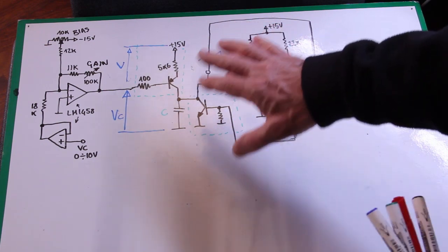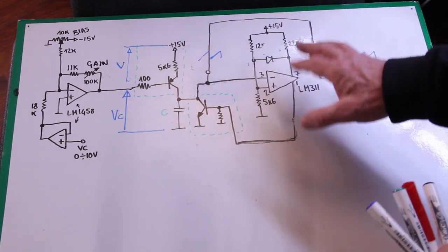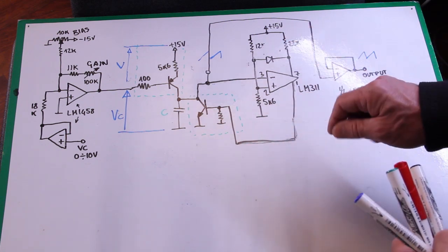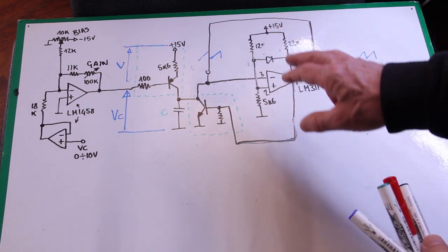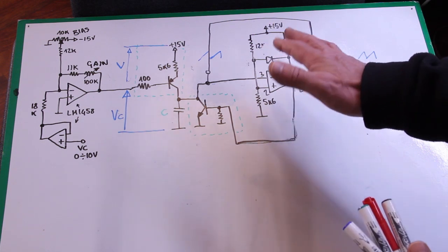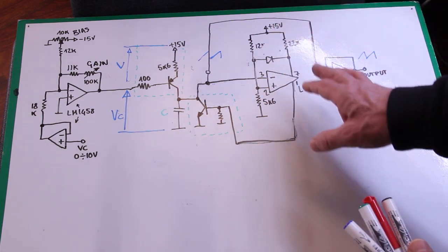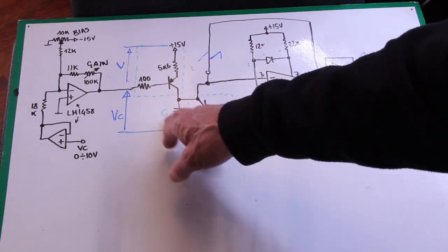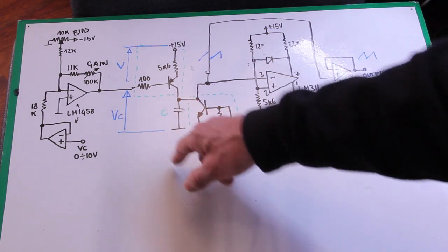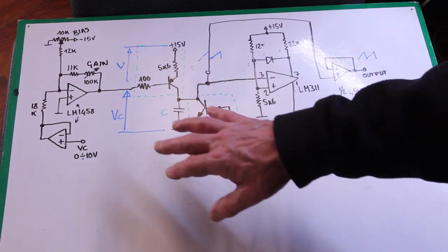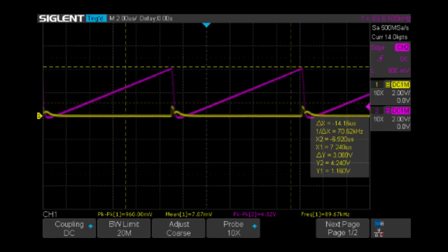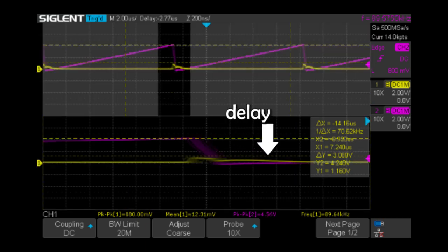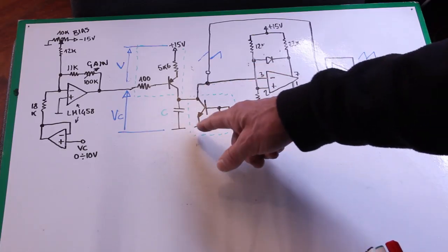First off, our circuit as it is now, while it is able to generate a nice sawtooth waveform, doesn't have a wide range of frequencies, as it starts from 50 kHz and reaches 200 kHz with a capacitor of 1 nanofarad, a frequency ratio of 4. While swapping the capacitor with 10 nanofarad, it doesn't work at all. Also, the ramp starts after a while, and this is clearly caused by a delay with a switching transistor that takes time to turn off, because the charges need to be evacuated from the base-emitter junction.